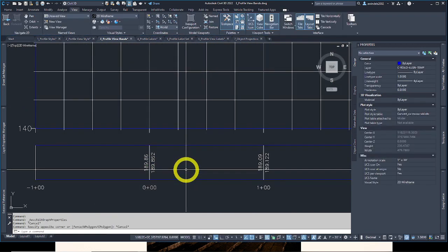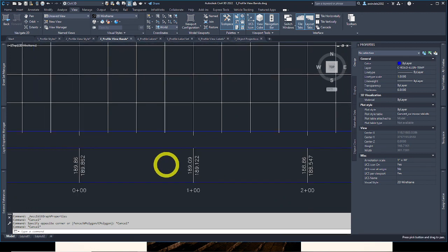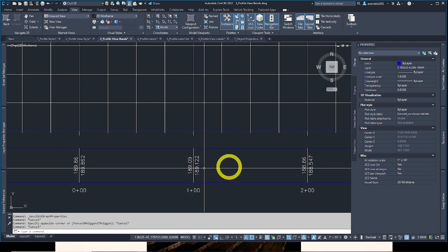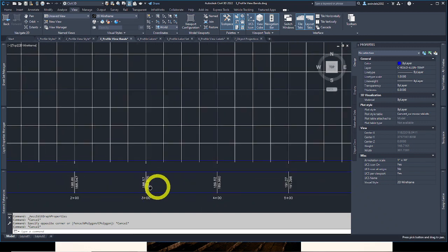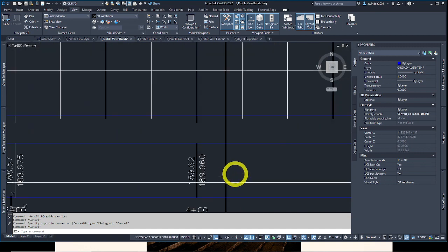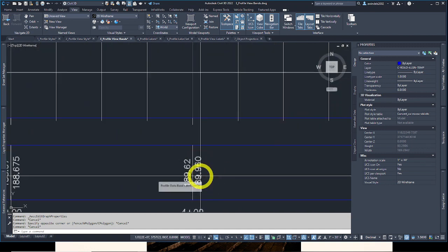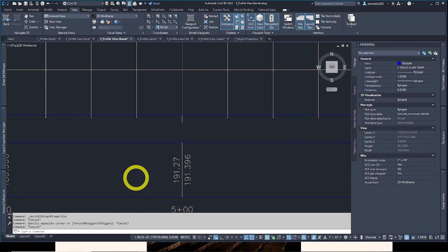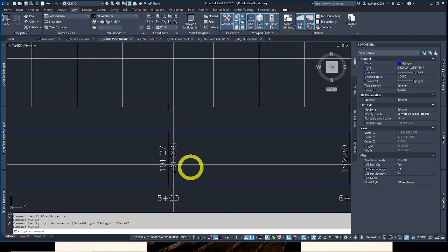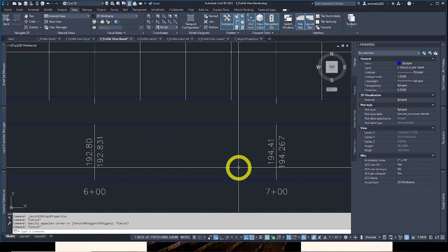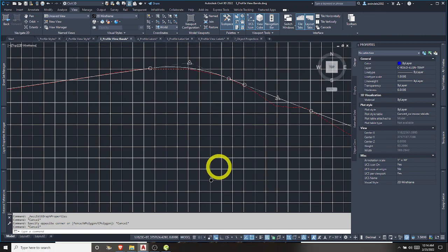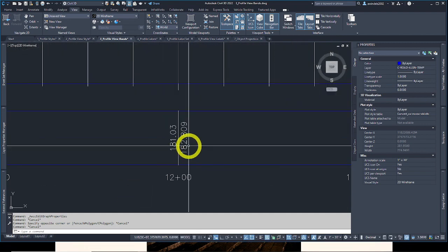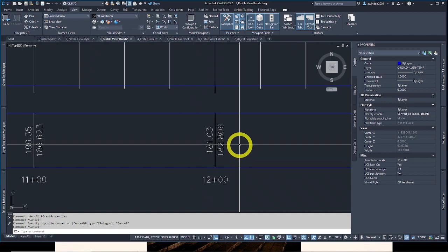And we have two different elevations, which is good. That's what we want. Elevation 1 is existing ground. Elevation 2 here is finished ground. We can see the difference. Someone could easily say, oh, okay, here's my station. Oh, here's my difference. I have a little bit of fill here because my design elevation is higher than my existing. It means it's a fill condition. Earth needs to be brought over, or material, or whatever. But they're very close to the same elevations. As you can see, they're almost touching all the way, which is conducive to what we have here. Most of the time it is almost touching. Here it's getting to be a little bit of cut and fill, over a foot and 2 feet.